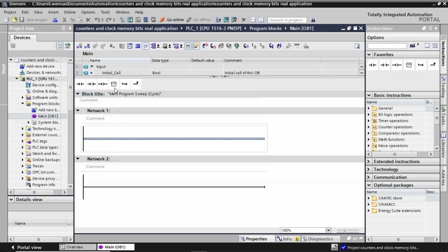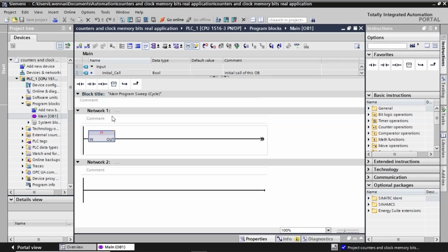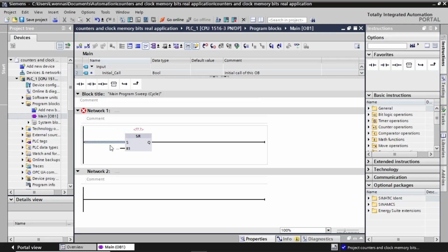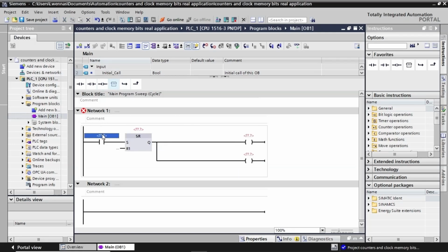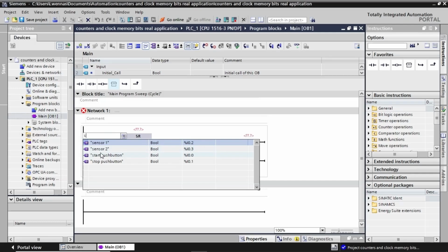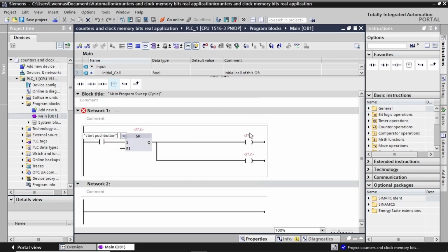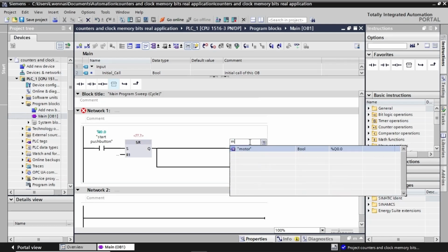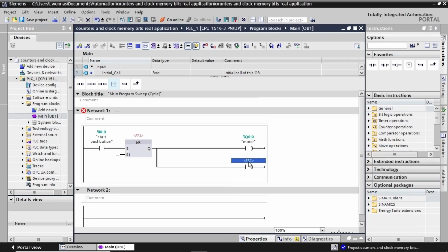We use an SR flip-flop for motor start and stop. We start first the code that runs the motor, then we go back to the conditions that stop the motor as we progress in the program. So, in the set we put the start push button to turn on both the motor and the green indicator light. We assign for each their addresses.